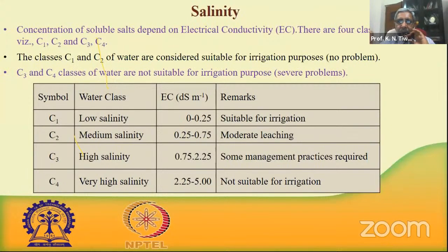The amount of rain minus the infiltration, at a constant rate of infiltration, whatever excess value there is will be generated as runoff. That runoff is used for design purposes, for developing the direct unit hydrograph or direct hydrograph. There we use this particular type of study. So it is not relevant to this particular study, which is for irrigation purposes.